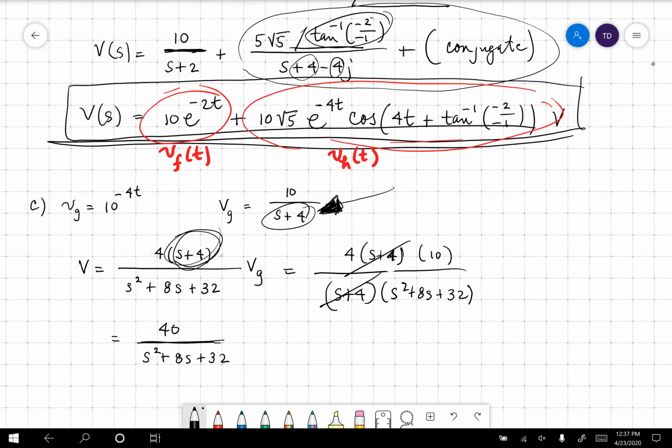When you plug in an input of natural frequency minus 4, this circuit, for the output that we have taken, filters it out completely. It filters it out entirely. And so you get 0 at the output. Here's what we're really getting at the output. At this output, V out, well, let's do it in the time domain. V equals 0 e to the minus 4t. We're getting something of the same form. The problem is its coefficient is 0. It's filtering it out completely.